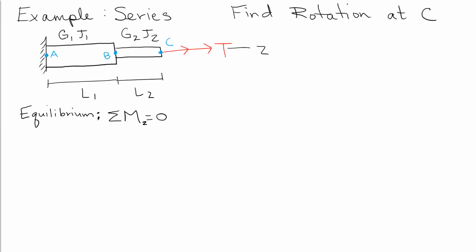Before, remember in the past when we were doing axial load, we broke this up and had 3 separate things that we could take force diagrams about? Well, it's the same now. We have our free body diagrams. We have our torque, which is going to have an equal and opposite torque on the other end, which means this has to be equal and opposite. Then there's going to be some reaction here, and this continues all the way down.